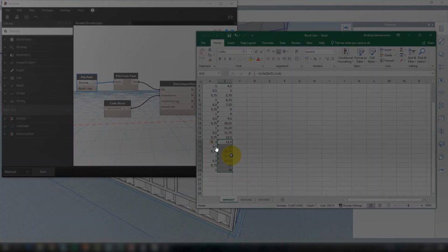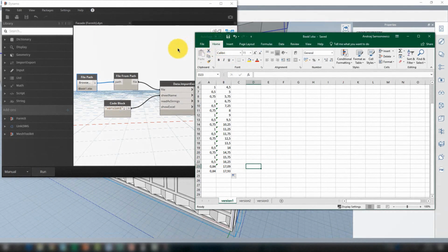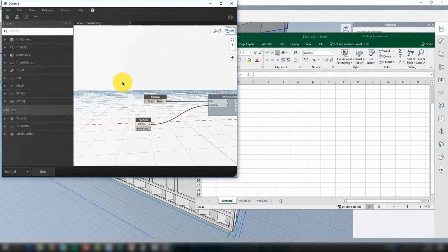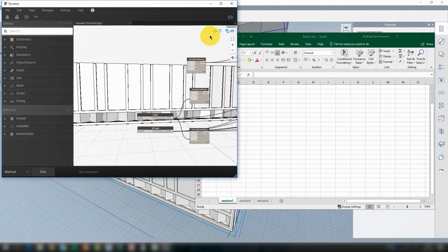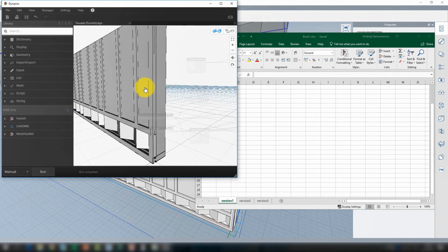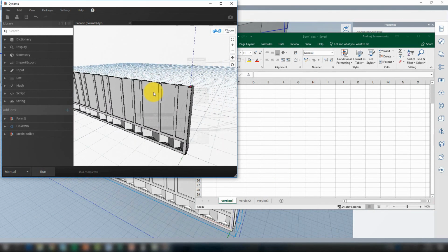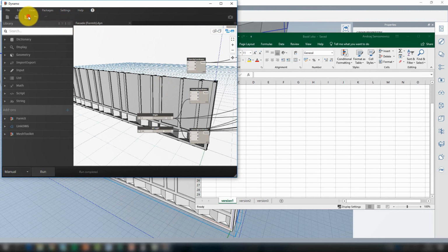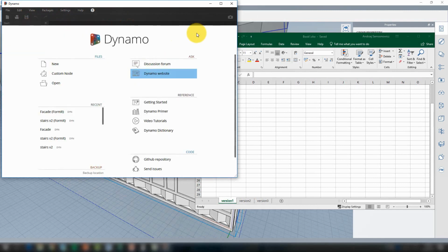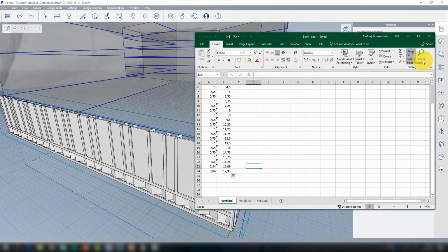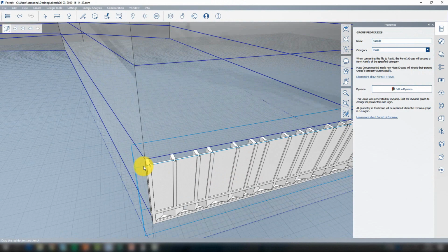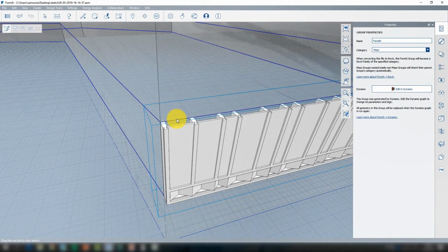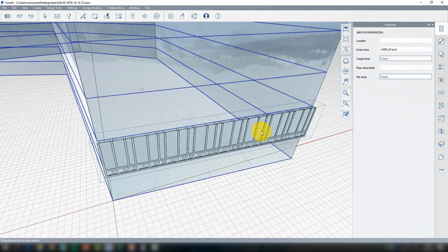Now you can see it. I'm going to save it again, like before. Here I can also control the height of the facade, the sill height, any kind of parameter. Then if I hit run in Dynamo, Dynamo executes the script and creates this solid, right? Of course, this solid is made of other solids, so later on I can also control what is panel, what is mullion, and so on, right? So here I'm minimizing, and I have a perfectly adjusted piece of the facade.